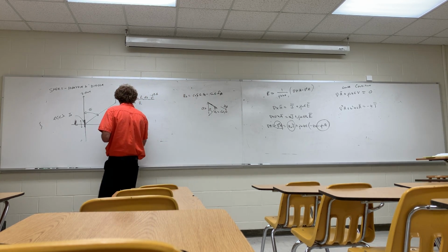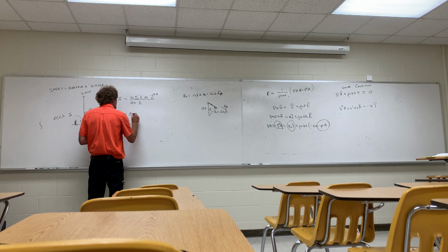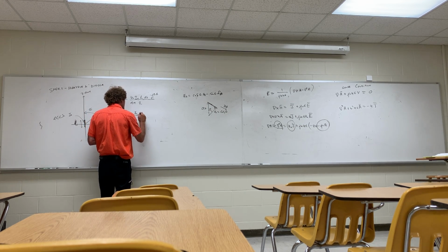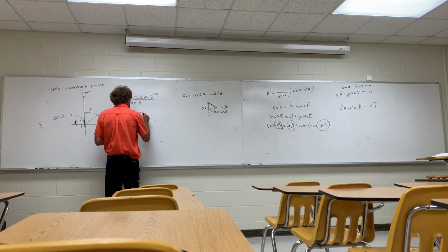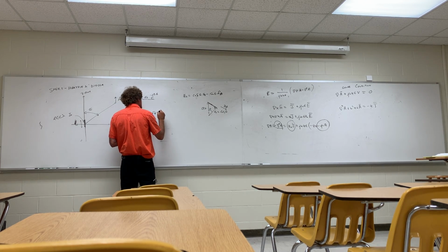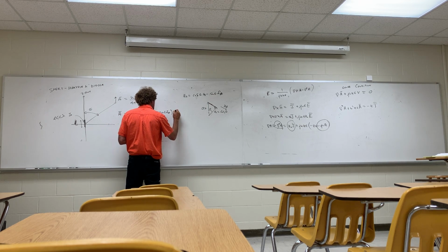So then when it comes down here, it's going to say A is equal to mu 0 over 4 pi, I naught times L over R, and then we put in cosine of theta AR minus sine of theta A theta, and then it's times e to the minus j beta R.